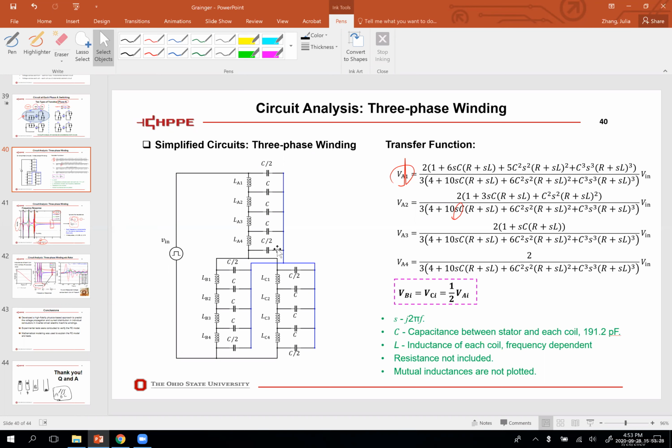And like you said, the insulation material that we fill in the slots has pros and cons. If you have higher dielectric strength, that's going to increase your voltage stress, but it also provides better protection in terms of insulation. With this modeling approach, we can easily predict the voltage stress for a new design and see if it meets their insulation design requirement. But if you ask me how they're going to improve their design, I don't think they will make a lot of changes if they don't see the voltage stress increase a lot for silicon carbide devices or when moving to 800 volts.